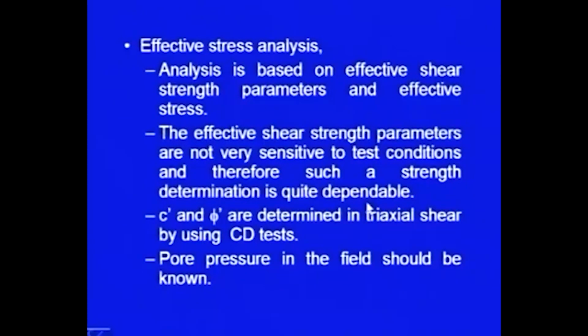In the previous slide we told you that in case of cohesive soils, we were assuming that the pore water pressure conditions are completely simulated. That is not possible. Rather, the effective shear strength parameters which we get are not very sensitive to test conditions, so their value is much more reliable.